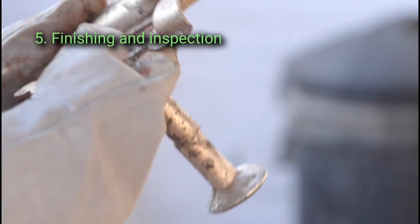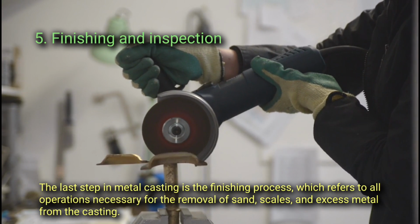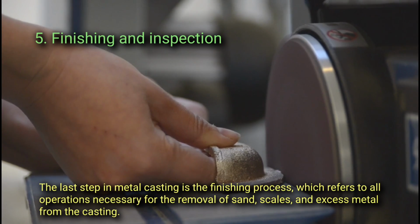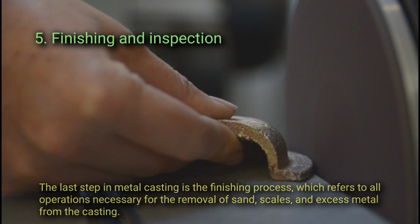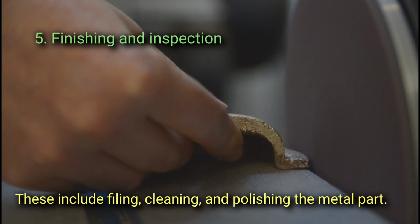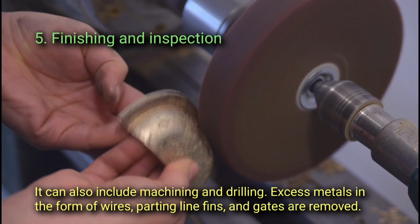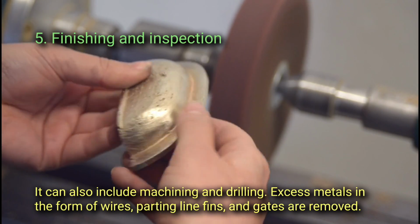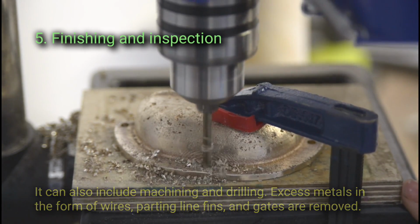5. Finishing and inspection. The last step in metal casting is the finishing process, which refers to all operations necessary for the removal of sand, scales, and excess metal from the casting. This includes filing, cleaning, and polishing the metal part. It can also include machining and drilling. Excess metals in the form of wires, parting line fins, and gates are removed.